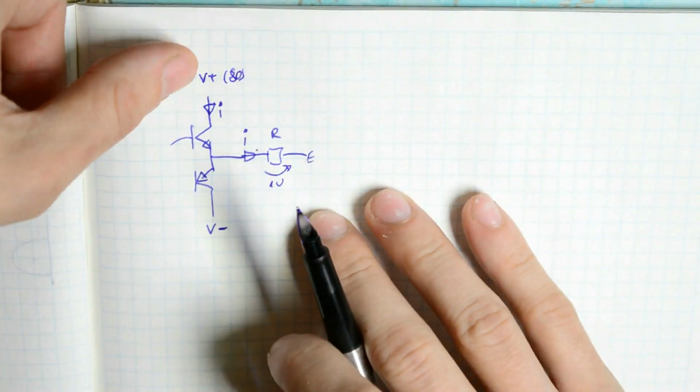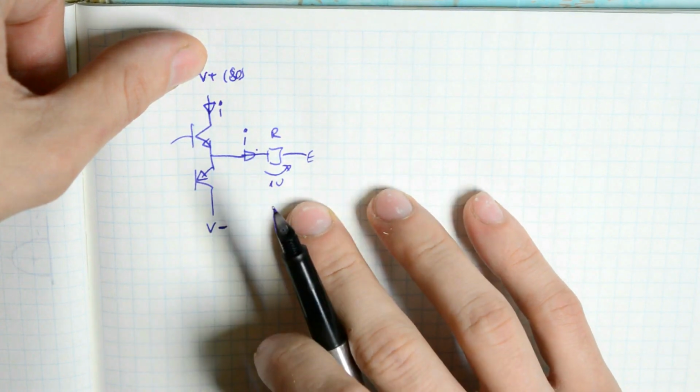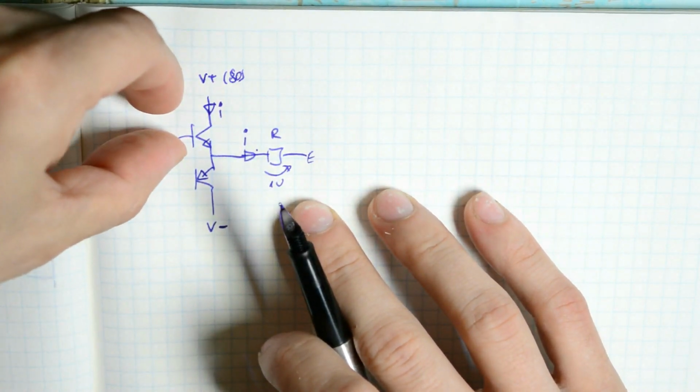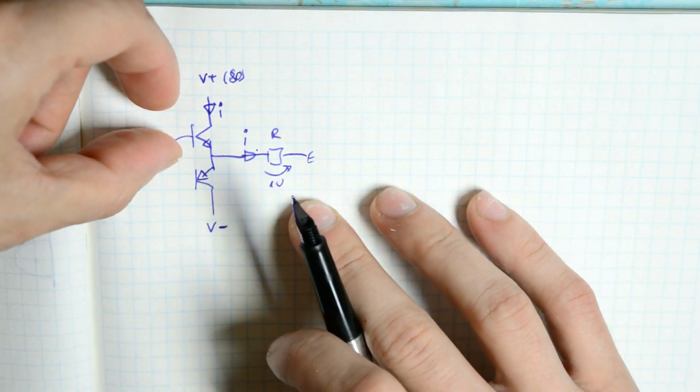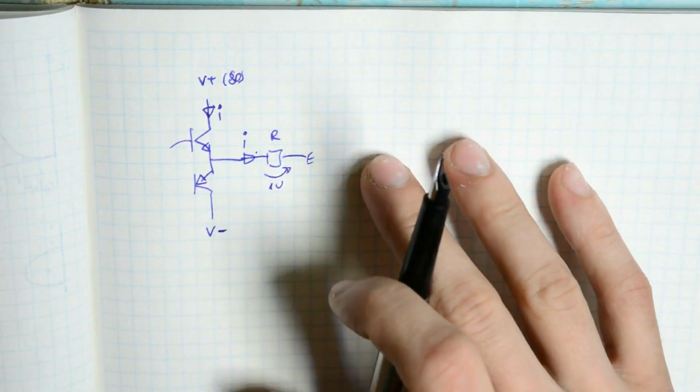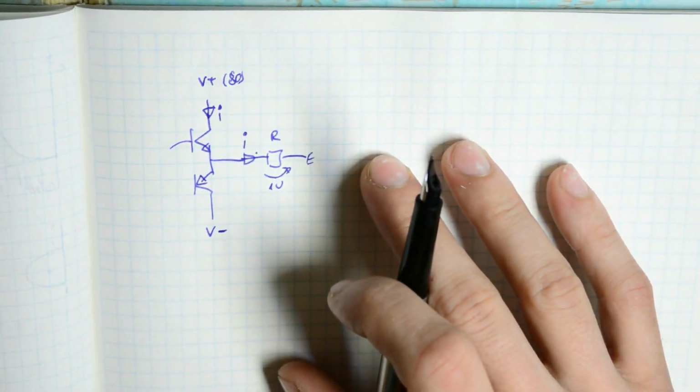But the same amplifier you also want to be able to use when you're at a party or something. Now in this case, since we're supplying at 80 volts and we're only using 1 volt, the rest of the 79 volts is a voltage drop on our transistor, meaning that we have very high power dissipation. So at light loads, this sort of amplifier is highly inefficient.